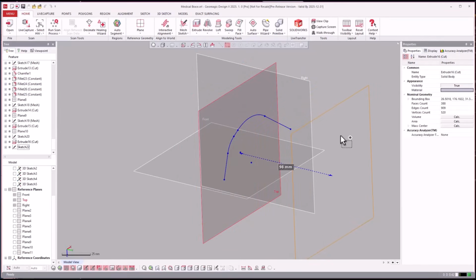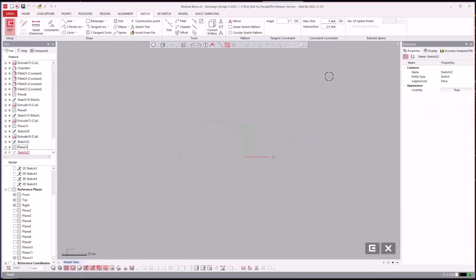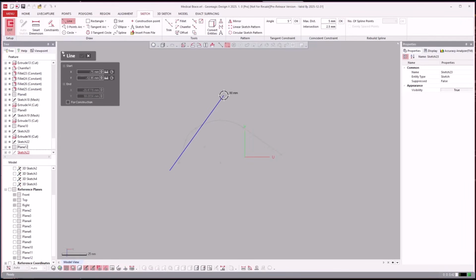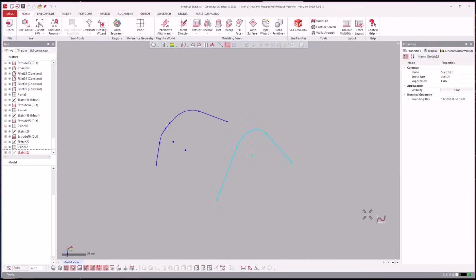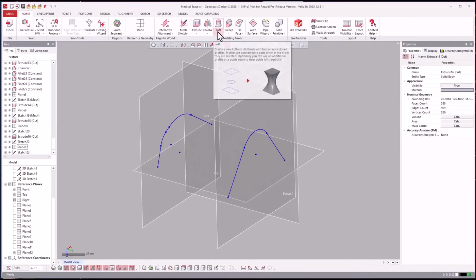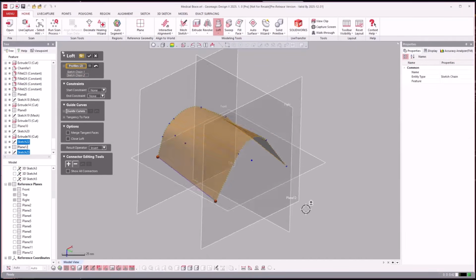and then I'm holding control. If you hold control, that's a shortcut. When you roll over a plane and hold control, you can offset a plane, which is really handy. And then now if I come over here, I'll just do 2 line segments and 1 fillet. And now, if you go to loft these, anybody that's done some lofting, you see that it's not too bad.